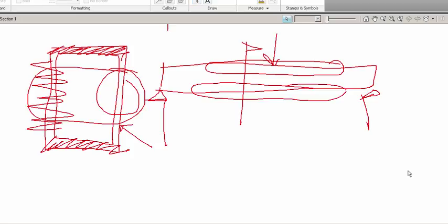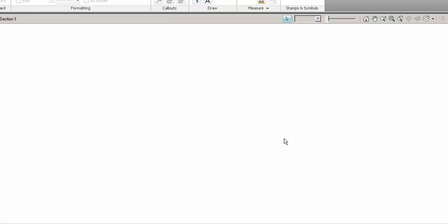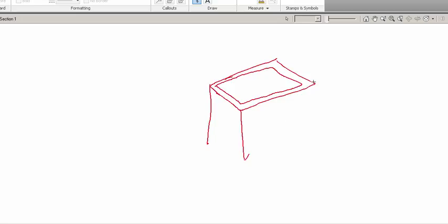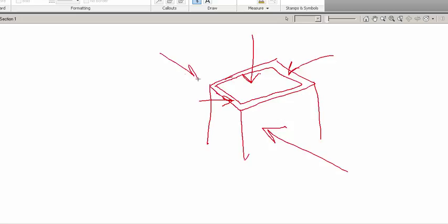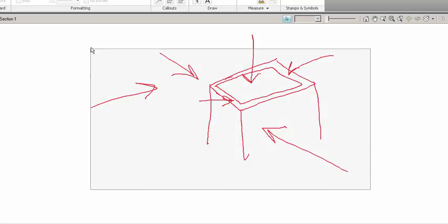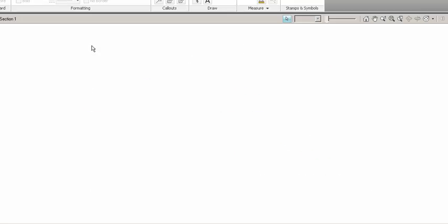Now that's not the same as a column. For example, when you have a steel column and you have something pushing down on it and maybe some seismic or wind activity pushing from the side, so there's a load pushing down this way and a load pushing this way, that creates stress in all kinds of different directions. So typically we end up wanting to use these extra walls more, especially when the direction of wind may come from this way or from this way. Having symmetrical parts often works out well for us. It's not to say that we don't use W beams for columns too, but steel tubes can be used very effectively for columns as well.